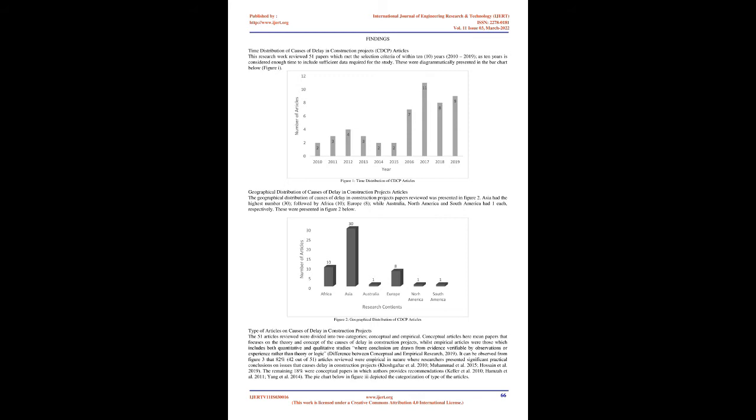Akagbi et al., 2013. Analysis of delay factors which affect the delay in completion of construction projects in Benin. Delays in construction projects emanated due to contractors' financial capability, owners' financial difficulties, poor performance of subcontractors, materials procurement of contractor, inadequate planning and scheduling, sluggish inspection of completed works by the consultants, and unavailability of equipment.